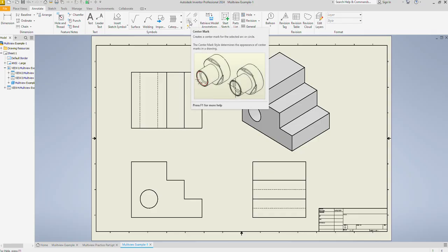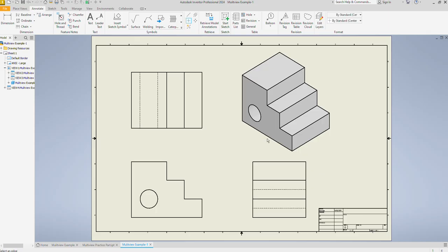So right here is the center mark. We just click on that icon and then we go to the edge of the circle, click there, and it will do that for us. For the next one, the center line, I'm going to use the center line bisector, which is this one diagonally up from it. So we click that. Now all we have to do is click the 2 lines, and in case it's the hidden lines, and it will draw a nice center line for us here.